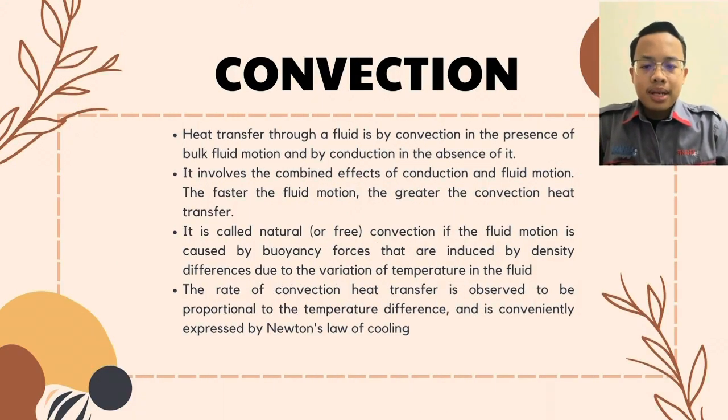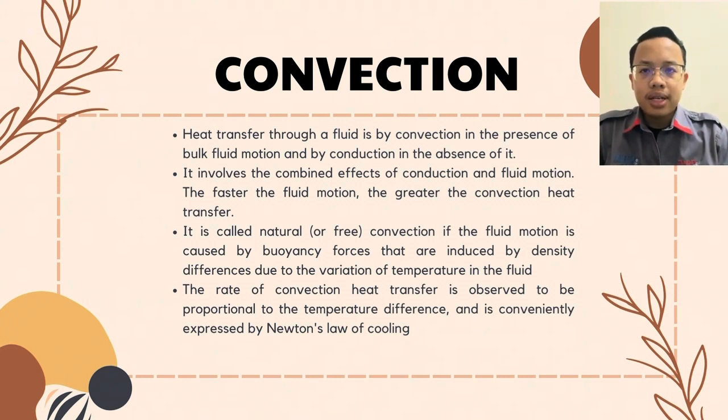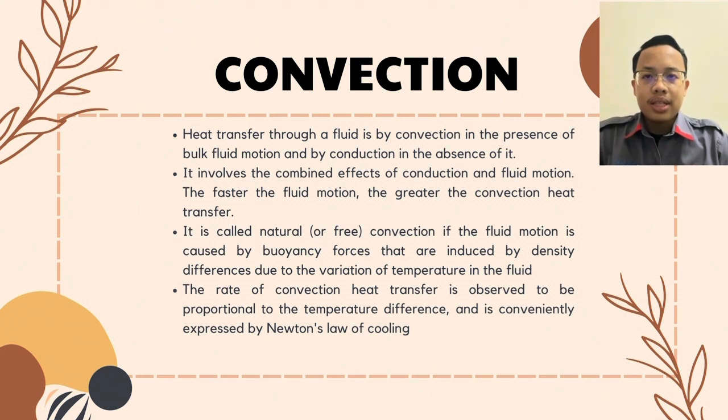Assalamualaikum. My name is Mohammad Eiman Salman bin Edham Lutfe. I will be explaining about convection. Convection can be defined as heat transfer through a fluid by convection in the presence of bulk fluid motion and by conduction in the absence of it. It involves the combined effects of conduction and fluid motion. The faster the fluid motion, the greater the convection heat transfer.